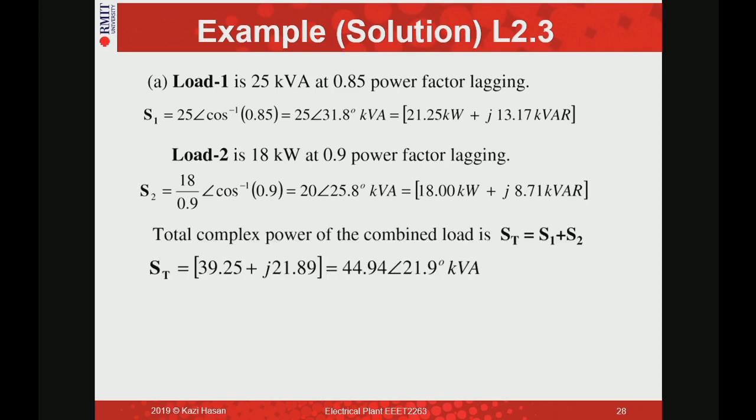The total complex power consumed by these two loads is S1 plus S2, which gives the total real power plus j total reactive power, and the total apparent power. And this is the angle of the combined load. From this theta, we can get our cos theta.